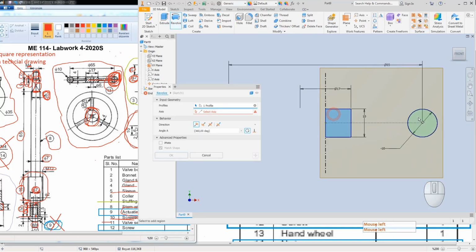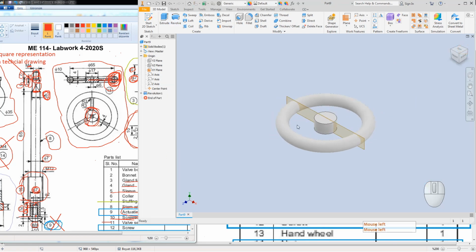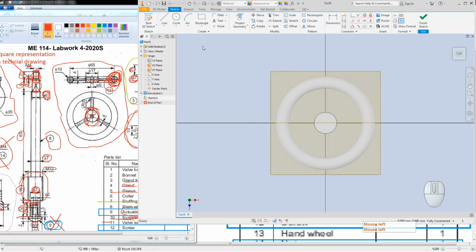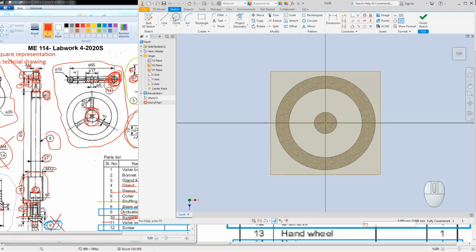Add the revolve tool, this portion around this one. I have the donut shape. Start a new sketch by using XZ plane for these arms. I start a new sketch like this with F7 tool. I will go inside, create a new line for symmetric condition. Make this line symmetric. I will make symmetric around these two lines. Okay.